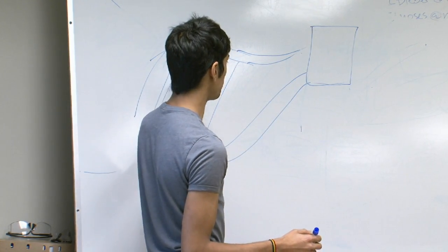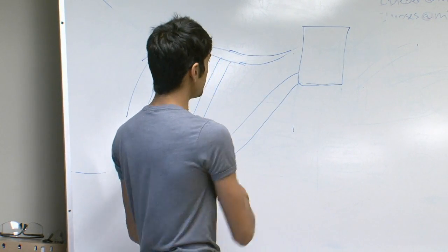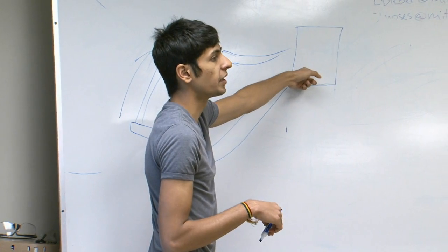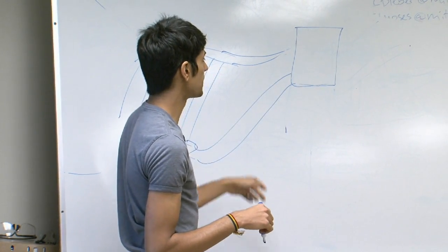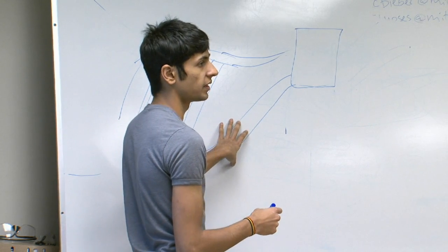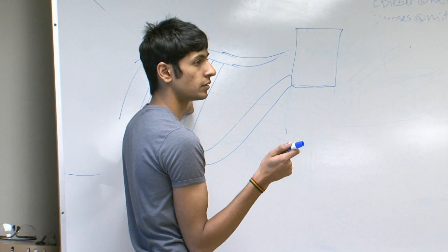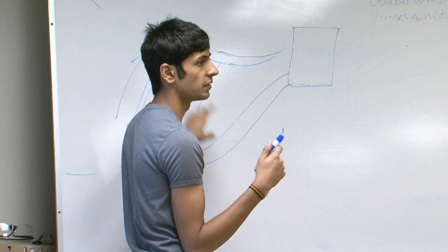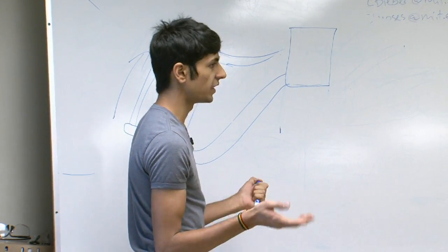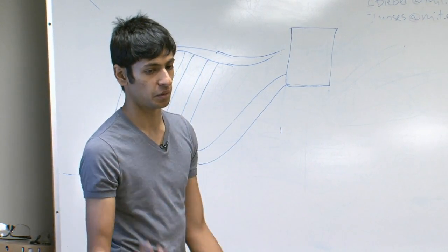So hot water will flow into this reservoir, and it'll get displaced by cold water. And so you're heating all of the water consistently, which is pretty cool because with a system based off of a thermosiphon, you don't need to throw in a pump or something like that to extract the water. What system is this? Just a heat siphon? Yeah, it's just a heat siphon. But yeah, it's just a passive way of doing the same sort of flow.